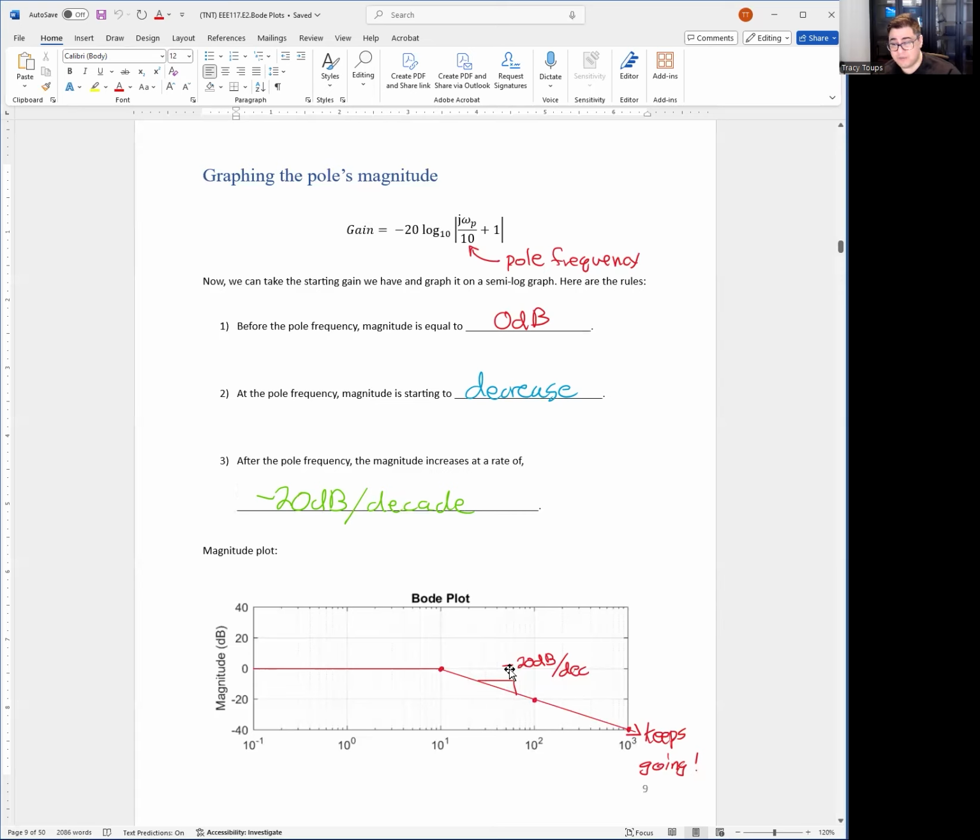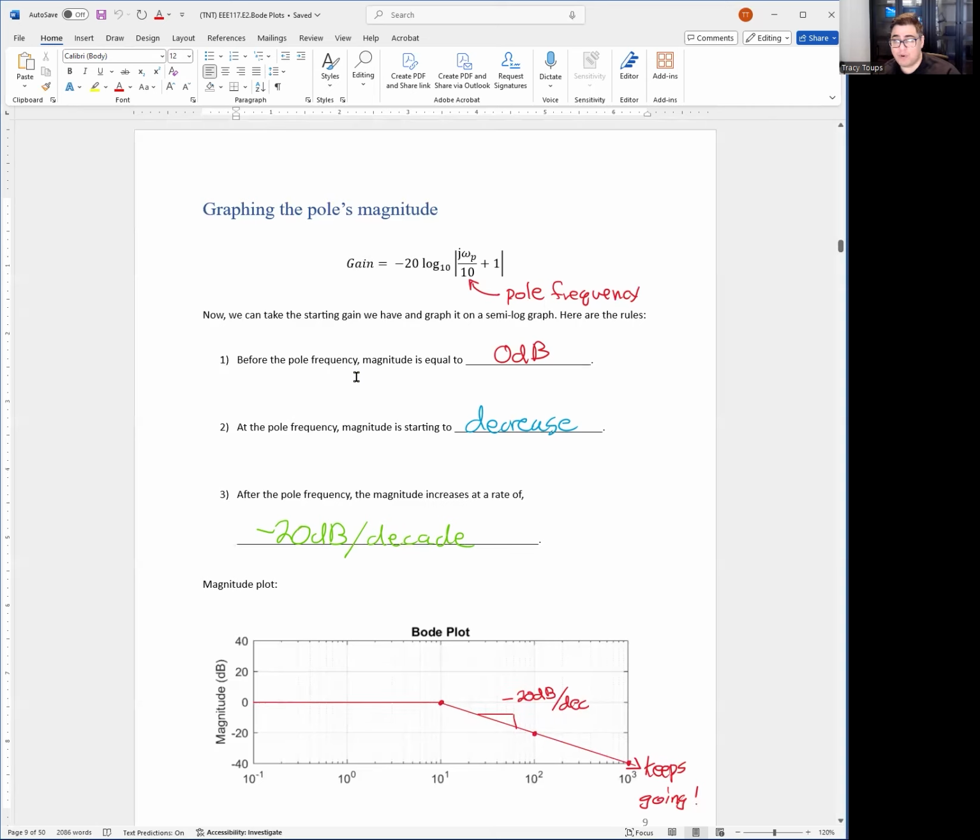Okay, you remember what is the gain of negative 20 dB? It's 0.1. What's the gain of negative 40 dB? It's 0.01. And you can see, I mean, it really kills the signal if you multiply by 0.1. Okay. So that is what poles do. They make the circuit attenuate and go down. The way I see it is you try to kill the signal. Okay.